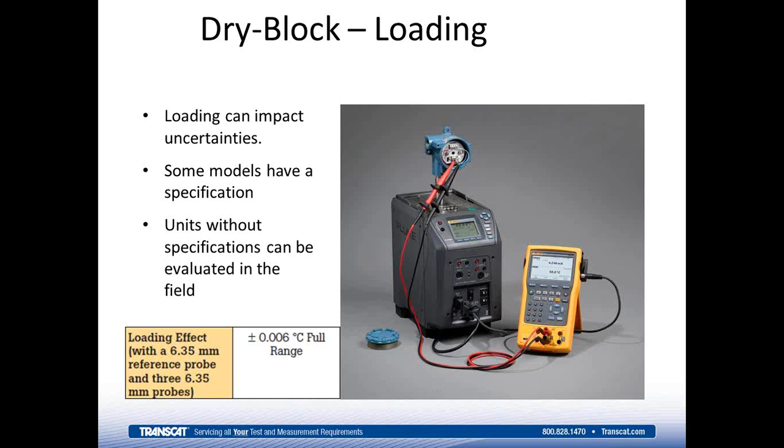For the instrument in the illustration here, the loading effect with a single probe, as opposed to 3 additional probes of the same diameter, works out to be about 6 millikelvin, or 0.006 degrees C.